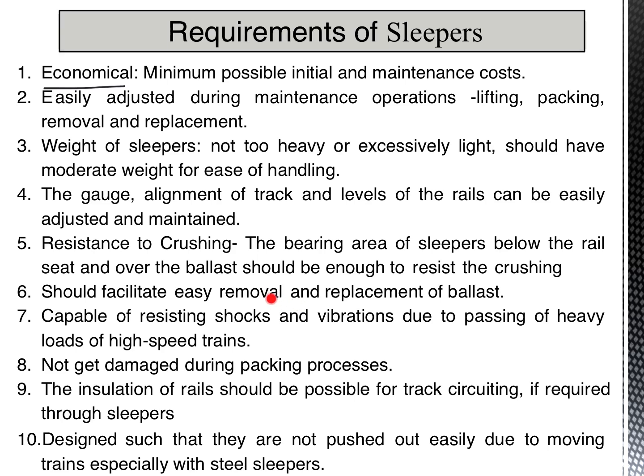The next is the design of the sleepers must be such a way that even if it is damaged for any reason, it could be easily replaced. And also during the packing process there should not be any damage to the sleepers; the material has to be chosen in such a way that there should not be any damage during the packing process. And the last requirement is the design of the sleeper should be such that they are not pushed out easily due to the moving trains, especially the steel sleepers. So these are some of the requirements to be fulfilled by an ideal sleeper.